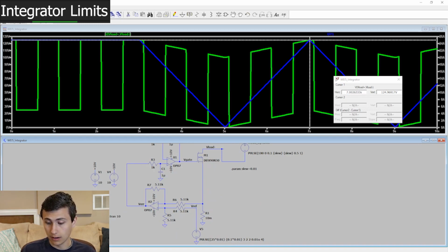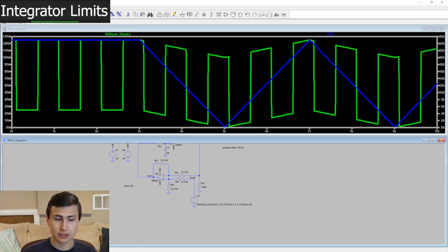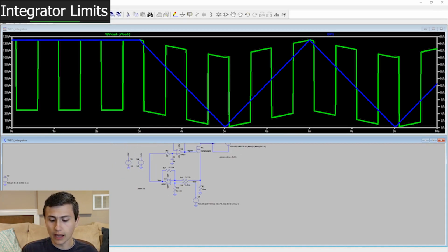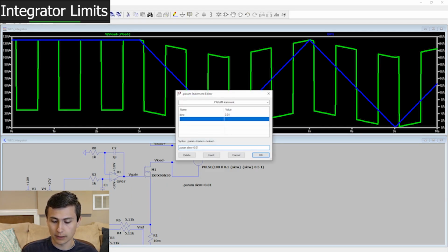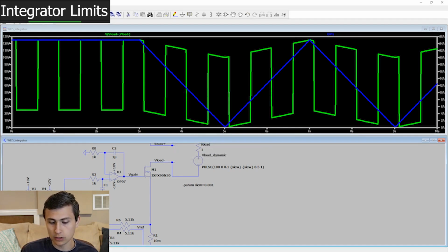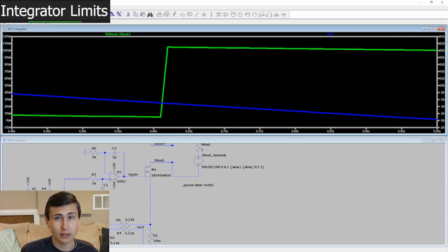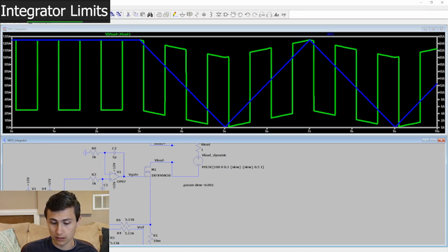Again, not ideal as far as an actual current source because of that. I really want to demonstrate how, with the PID, there's limits here. Only having the integrator introduces some limits. And I want to expose that by increasing the slew rate by an order of magnitude. So these sharp transitions right here are about to be 10 times steeper. And I just want to see how that impacts the regulation.